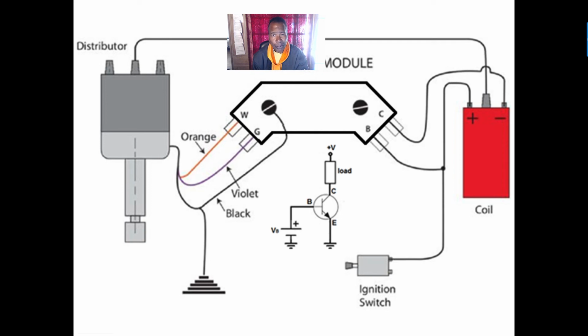So I had a car with no spark, and I want to know if my input side is working. I'll put a test light here and see if it blinks. If it blinks, that's telling me my module, transistor, coil, and pickup coil inside here are all working. And my problem, if I had no spark, is either a coil or coil wire. This coil wire does go bad.